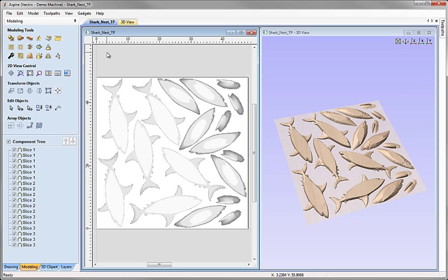Before we create our toolpaths, we want to generate vector boundaries in order to contain them. The slicing presents an interesting situation because we have these flat areas on the slices, and because they're the thickness of the material, we don't really want to create a toolpath over the top of those. The most efficient way to cut each slice is just going to be to cut the 3D area around the side. So we're going to have to create a reasonably specialised set of boundaries, and to help me to do this, I'm going to group together some of our components.